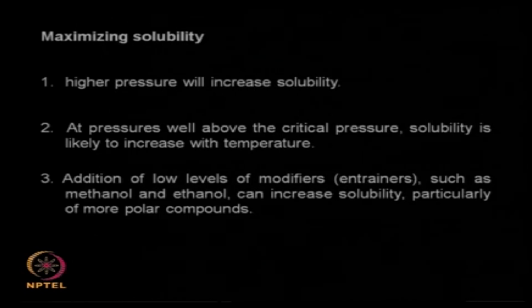So when I add a little bit of methanol or ethanol, then it is very good for polar compounds. Okay, when we talk about polar systems, nowadays supercritical water is also becoming very fancy, but the main problem with supercritical water is the pressures are extremely high when compared to CO2. That means the hardware design is a big challenge, number one. Number two, supercritical water is also very corrosive.